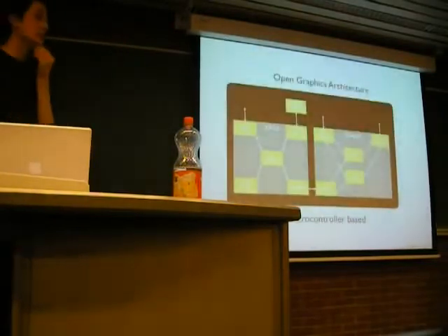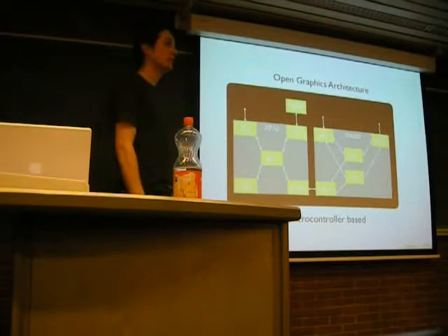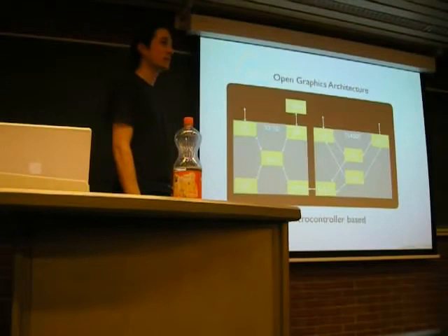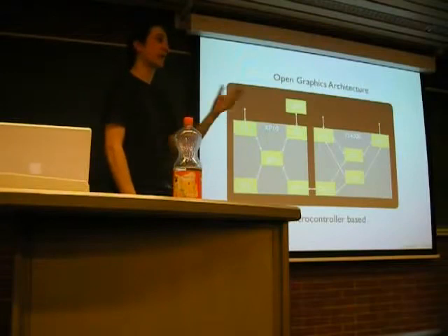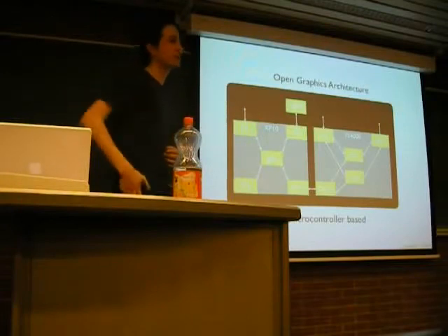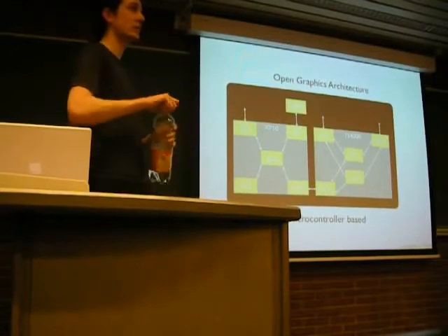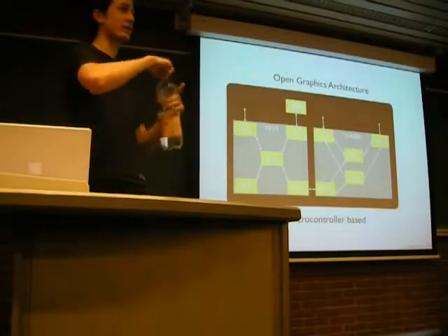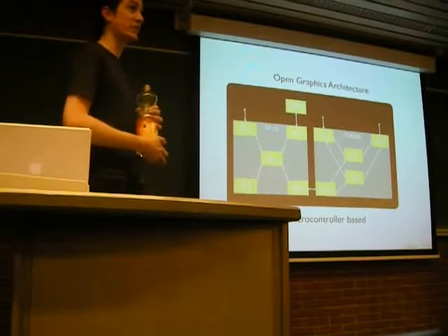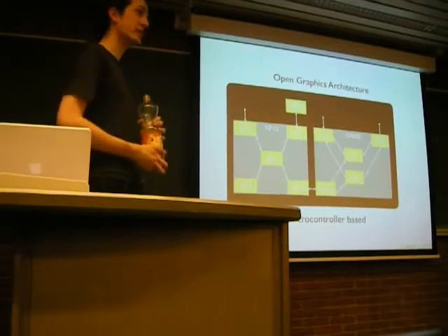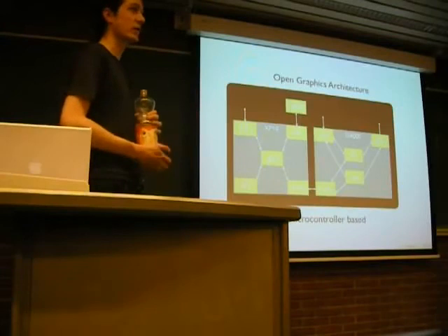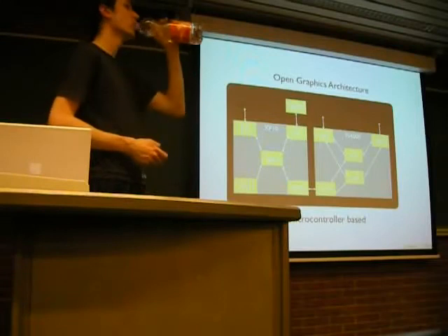Is the gate array actually programmable during runtime, or is it only programmable by the JTAG interface? It's only reprogrammable through the JTAG interface, and then on top of that you can of course create something like a microcontroller and then program it. No, we're not talking about that, because it would be pretty cool if you could just transform it. Yeah, now reprogramming the chip itself by use of JTAG takes a second. Too long, yeah. But it's a second. I think you just have one shader. Which can do that, but they're probably too expensive.